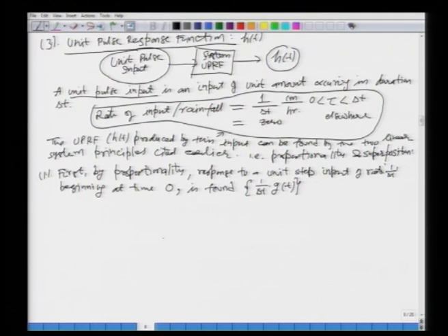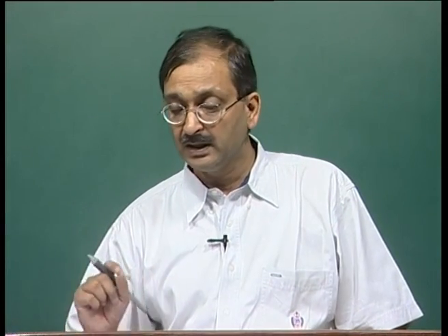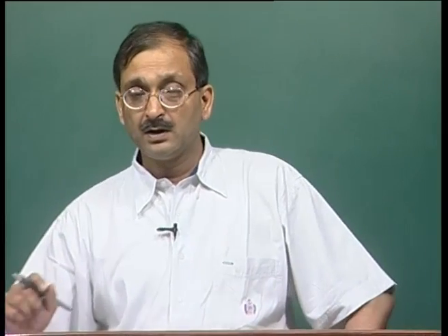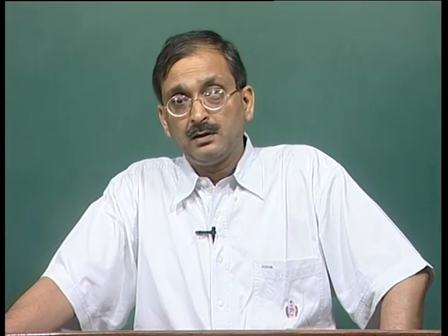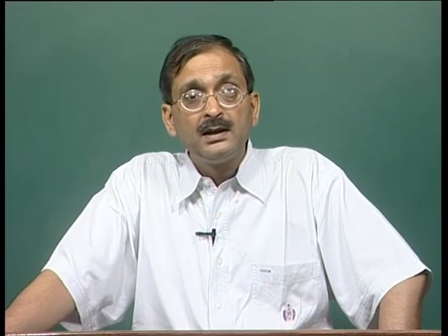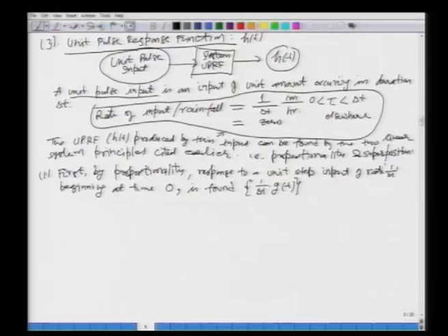Okay. So, we are using the principle of proportionality. You know the unit step response function g, let us say, that is given to us. That is the g of t. It is the response from the function due to what? Due to an intensity of 1 centimeter per hour, all right, but it is a linear system. So, we can get the response from the system when the intensity is not 1, but x, all right, and that x is 1 by delta t here. So, all we do is we multiply this g by 1 by delta t, which is the intensity of rainfall, all right, for a certain time, only delta t. So, this is what we do, that is the first step.